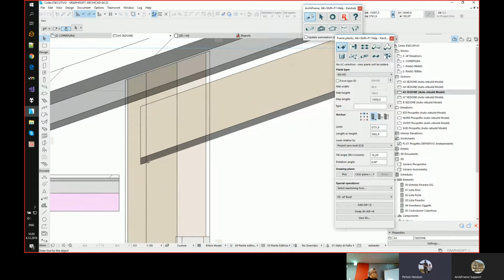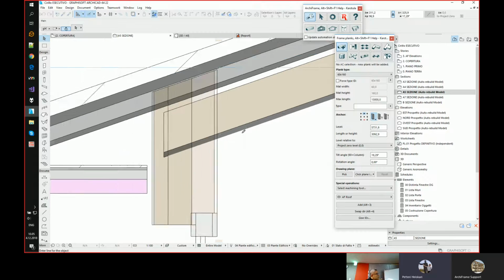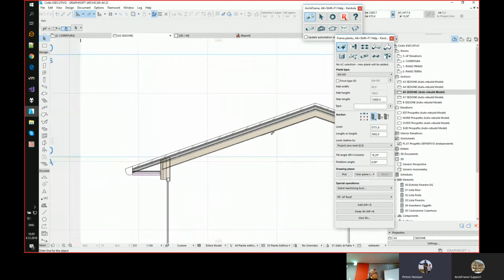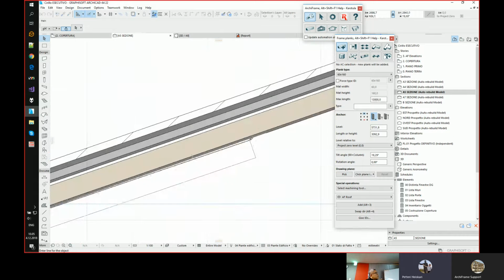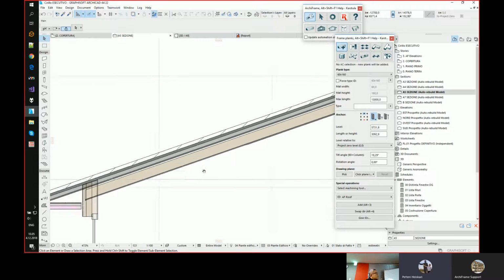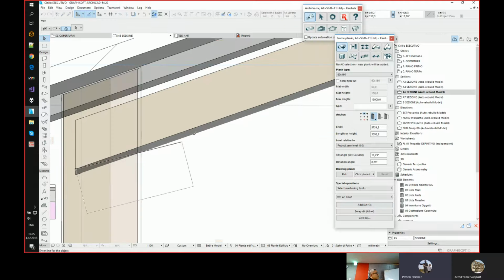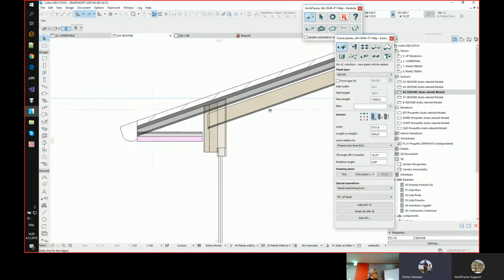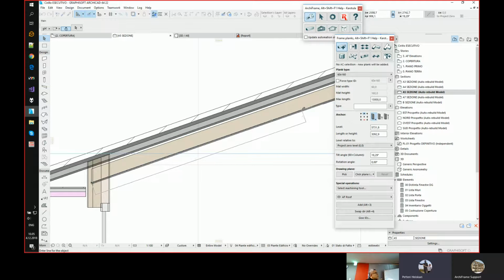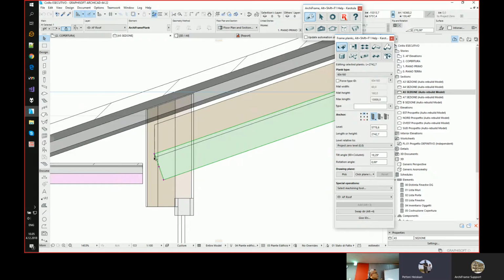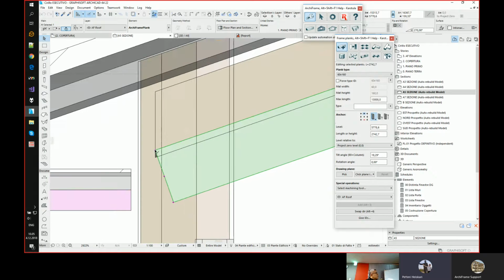I know this model, this Italian one, so we need to place the rafter below the ArchiCAD roof, and here at this section I get the angle. Actually, I don't get a snapping line from this. I need to put it a bit higher. This has the exact line. So the first rafter like this, and then I'll stretch it from these pink hotspots here.